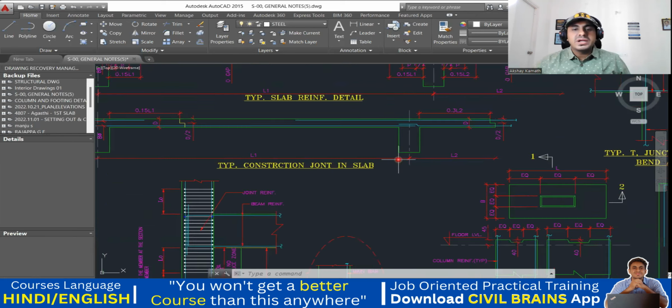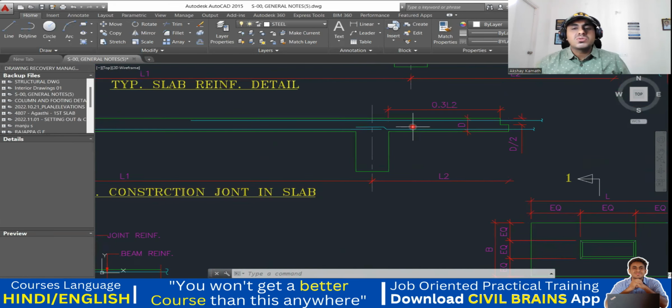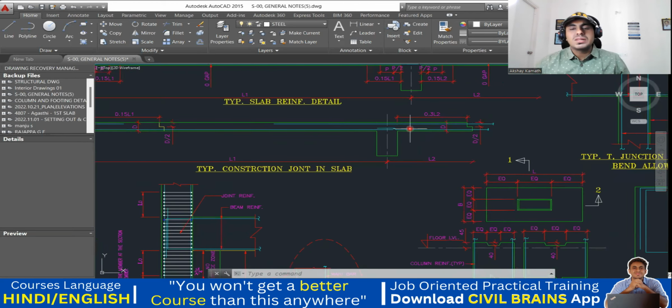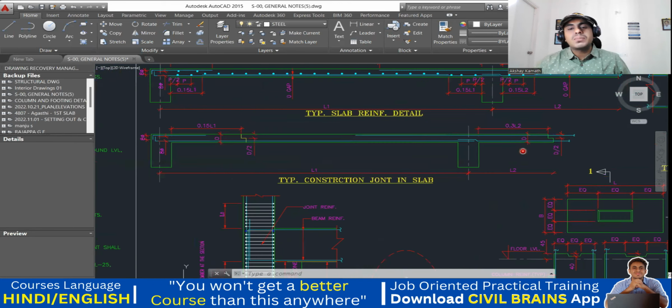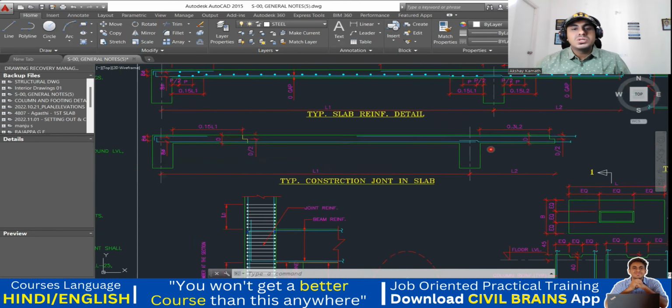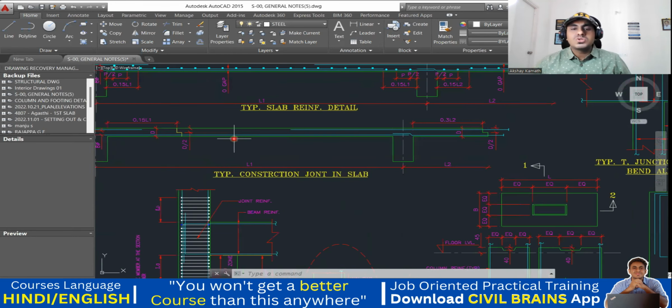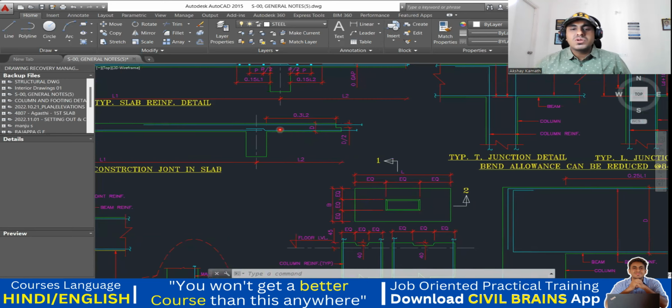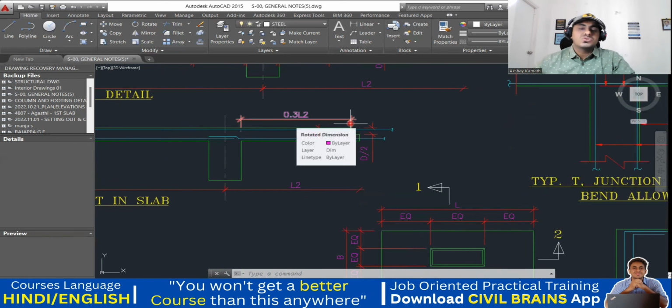Because tomorrow on the site, let us say you don't get a drawing like this, and something happened on the site. It started to rain so heavily that you wanted to stop the slab concreting. So in that case, if you have just started the slab and you are at the discontinuous support, you can go up to 0.15 into L and you can stop. But if you have concreted for almost 2 hours and you are somewhere close to the continuous support, then 0.3 into L, you are supposed to stop it.